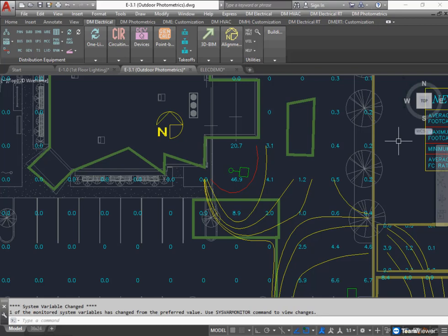So we don't have any way to adjust a single fixture and say, okay, this one fixture is 8 feet long, but we need to do the IES file in here twice for it. Just create it as a 4-foot section, put in as many as you need, and then the calculations will be based upon that.